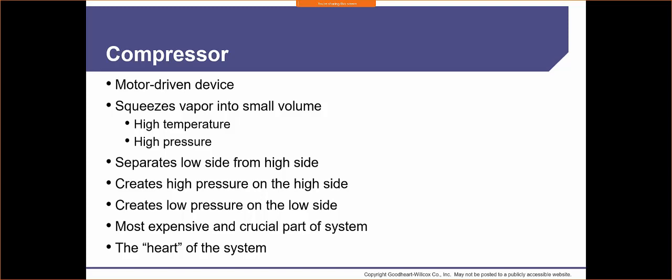As soon as that compressor starts up, my high side is going to increase, my low side is going to decrease. All right, I've got a suction naturally forming on the low side as the compressor pulls in that refrigerant, and then on the high side, I've got that force. It's just pushing that refrigerant through, and one feeds the other.